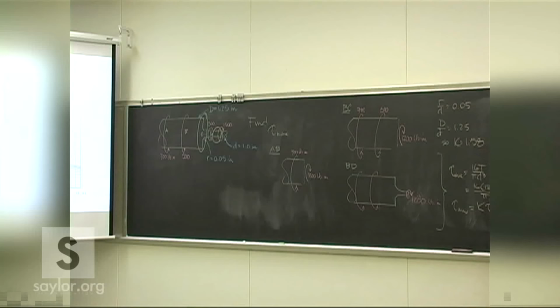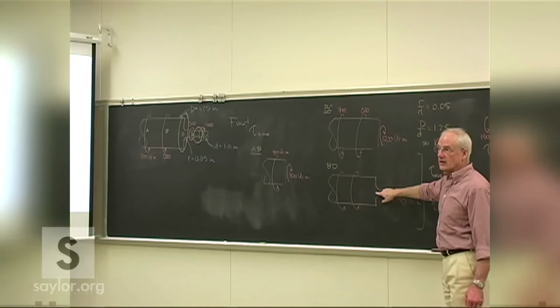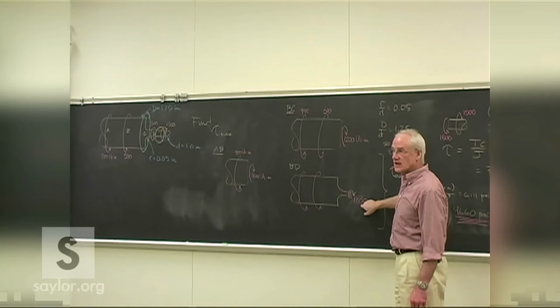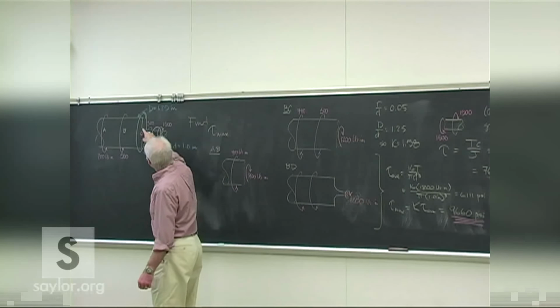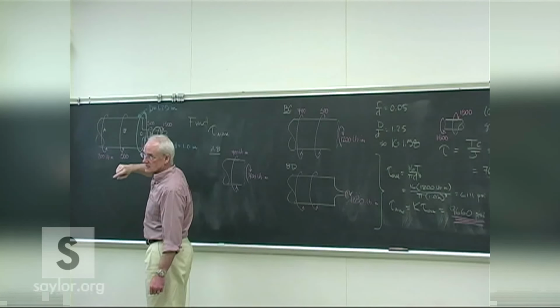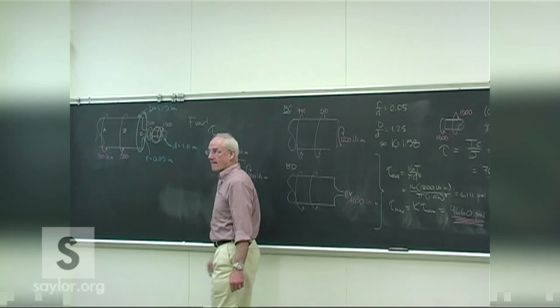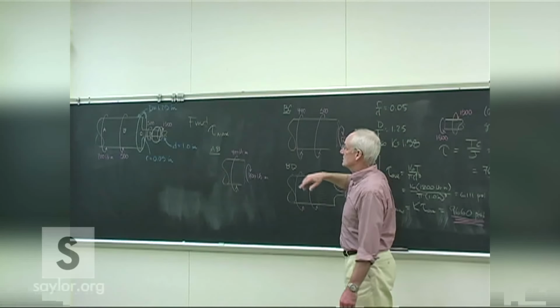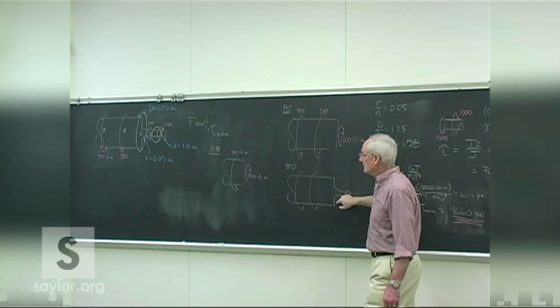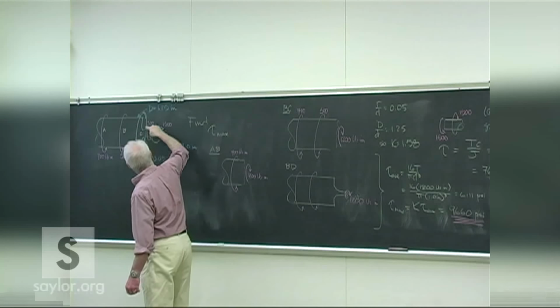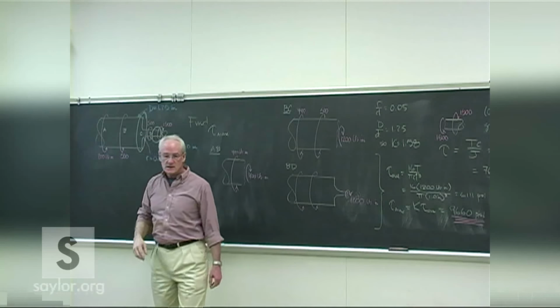Well, you have to look at both. This had the greatest load on the smallest diameter, so we had to look at it, but then we also had to look back at the fillet area, even though the load was not as great. So the area of concern is going to be right at these corners, because that's where the stress concentration factor applies. So you only apply K where the fillet is? Yes, because that's the whole point of the stress concentration factors, these area changes. So that's why I circled that as a region of its own and compare those two numbers.